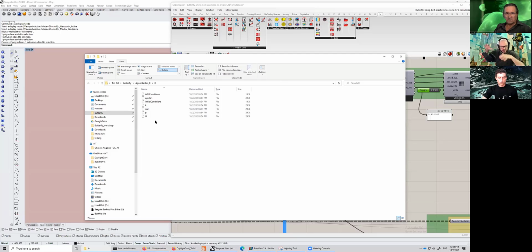So for each surface inside, for all the wind tunnel surfaces, for your geometries, all the stuff that you had to do manually before, Butterfly has done everything for you. It also has the initial conditions of your wind profile. So this is not just one wind velocity, it's a whole logarithmic wind profile, right? It's one different wind velocity at different heights. All this was done automatically for us, right? By Butterfly. We don't need to care at all about it.